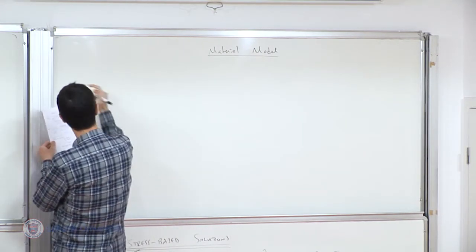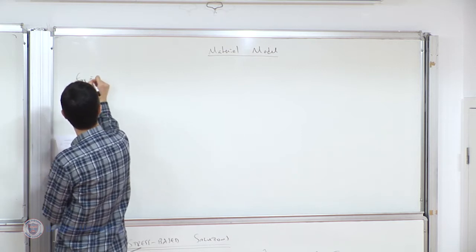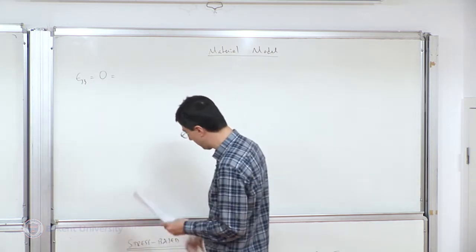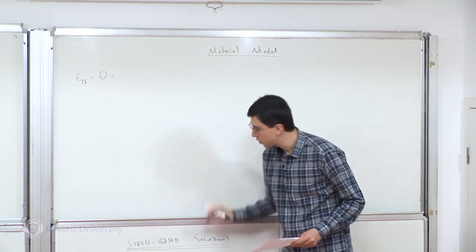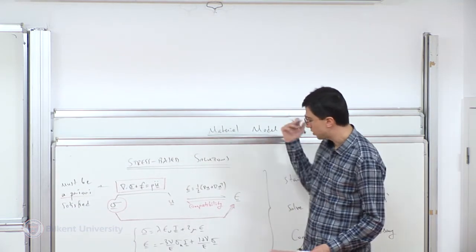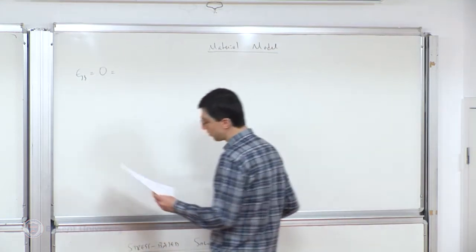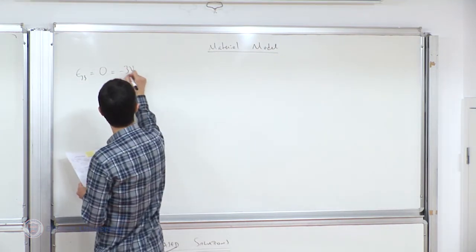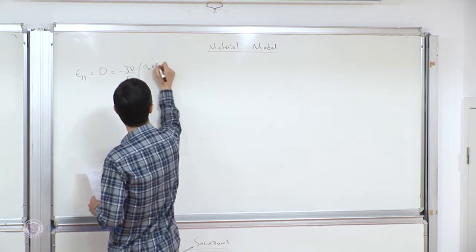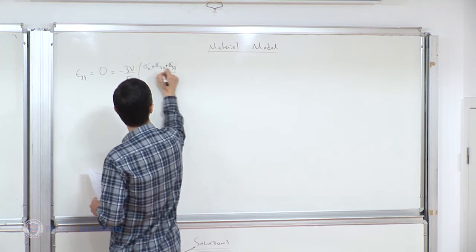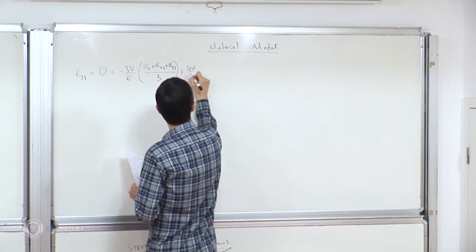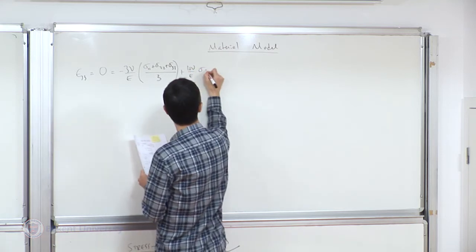So what is it? It's something that we would like to find out based on our isotropic linear elasticity relation. So I set epsilon 3, 3 equal to 0, and I'm essentially following this relation. This is for plane strain, that is for plane stress, which I'm going to examine. So epsilon 3, 3 is equal to 0. It's minus 3 nu over E times the hydrostatic stress, which is the sum of the diagonal components divided by 3, plus (1 plus nu) over E sigma 3, 3.